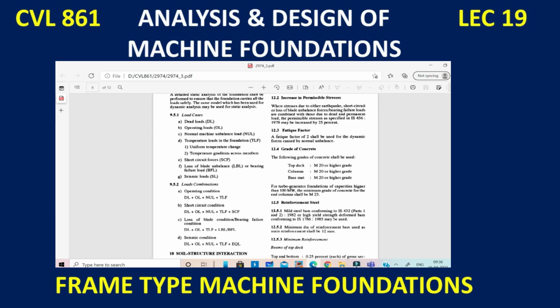Fatigue factor: it says that a fatigue factor of 2 shall be used for the dynamic forces caused by the normal unbalance. So when we are doing this static analysis and the load combinations, we must use a fatigue factor of 2. It is used when we are doing the stress calculation, but need not be used when we are obtaining the displacements.